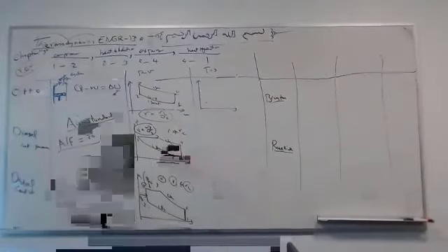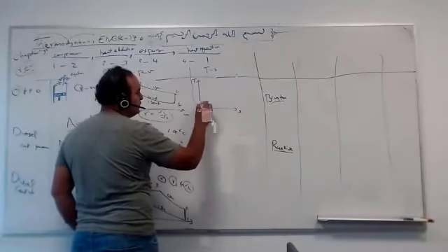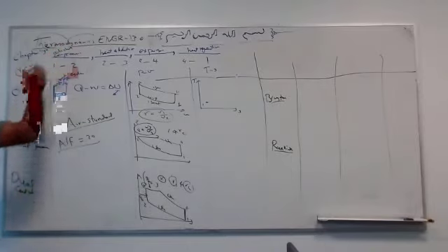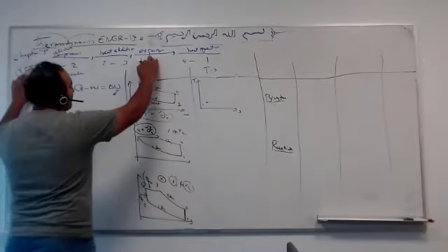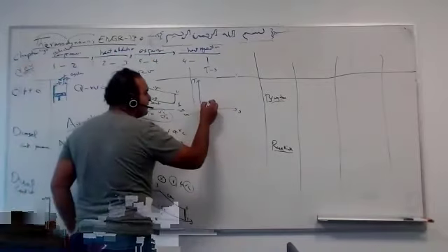So tell me, Thani, for compression, how can I move here? Horizontally or slanted? How can I move from 1 to 2? You go up. Horizontal or vertical? Vertical. Why? Because it's reversible adiabatic, that's why it's isentropic. Isentropic compression, isentropic expansion, always. So here we move vertically, okay?